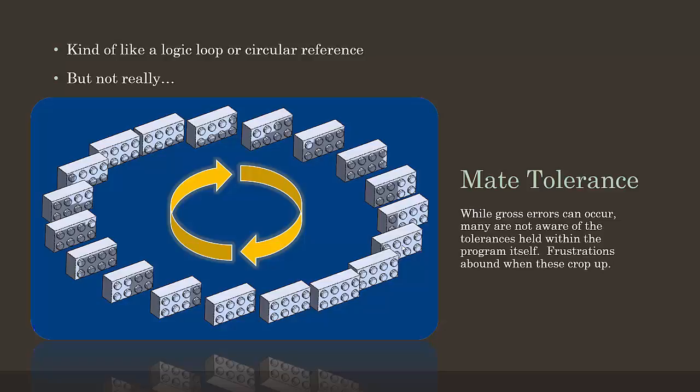So what I've noticed is that we go down 8 decimal places, but I think there's math beyond that point happening. I think it's only displaying 8 places, but it might be going down to 12 decimal places. And I think there's a little shift of number way, way down there. The other place that you're going to run into this is if you're running metric numbers with inch numbers as well. Even if I say that needs to be 4 millimeters, but you're working in inches, I think there's something that happens there.